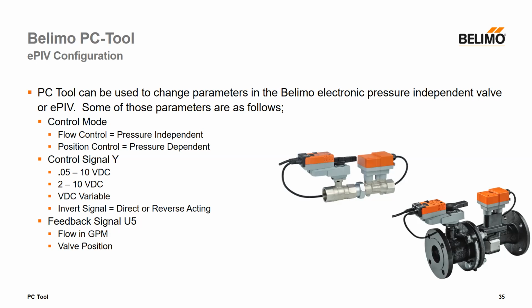If you need multiple parameters, so say you want to know valve actuator position, flow, and command, or you want to know position and GPM at the same time, we make a -mod version of the EPIV. So the actuator part number would be EP2-mod. The mod, of course, stands for Modbus. However, it's just a simple RS-485 card in there, and an EP-mod version can also be configured for BACnet over MSTP. So if you need both GPM and valve position to do a critical zone reset, more than likely you'll want to go with the communicating version of the EPIV.